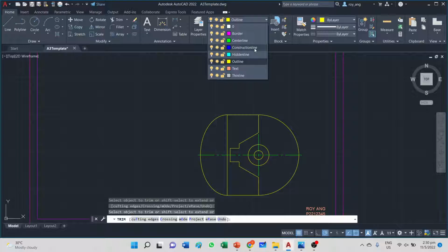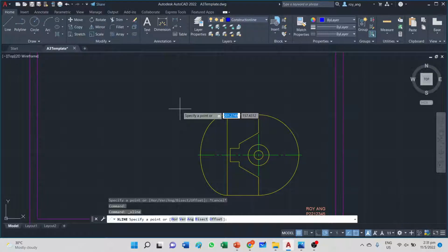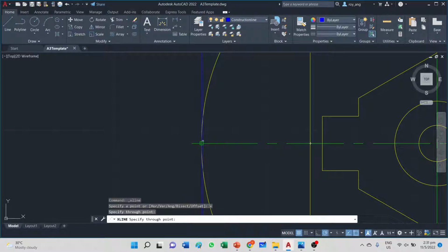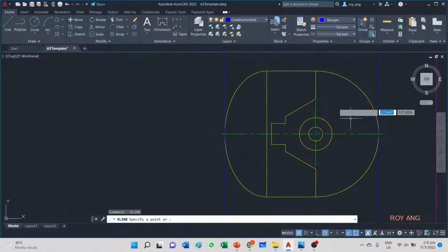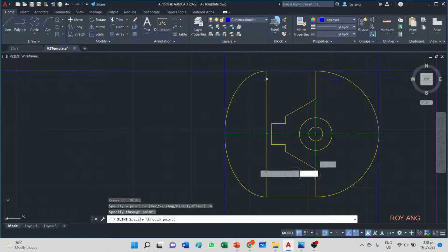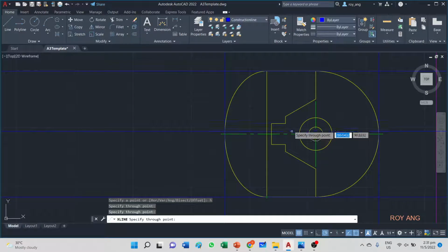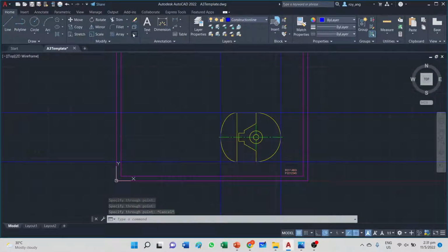And this is where I will switch over to the construction line, and I will create my construction lines, right? And I'll put vertical, and I snap it to the extreme of my plan view. Right now I'm going horizontal. Okay. And I'm going to offset by 20 millimeters.